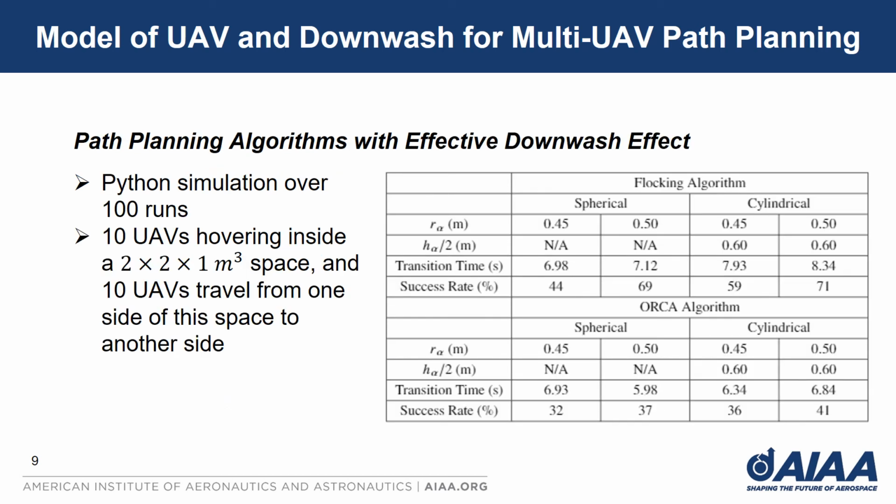Python simulations over 100 runs are done to test the performance of the cylindrical models of the flocking algorithm and the ORCA algorithm under effective downwash effects. To create a 3D dense environment, we have 10 UAVs hovering inside a 2x2x1 space, and another 10 UAVs traveling from one side of the space to the other side.